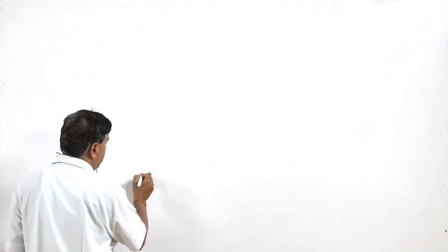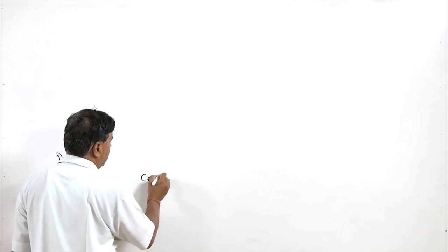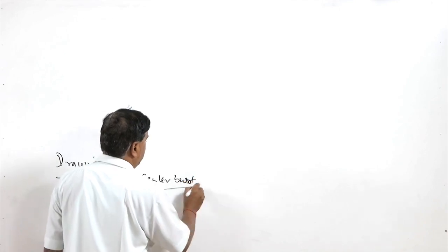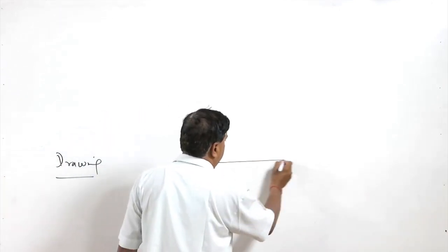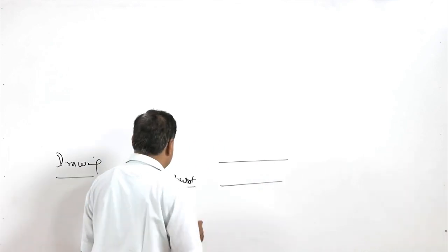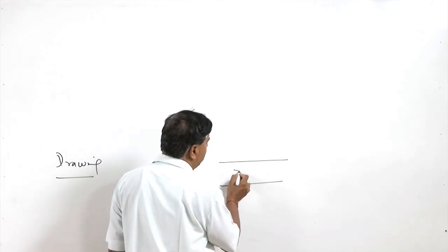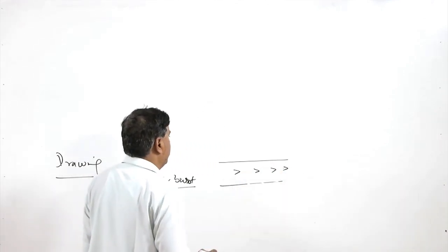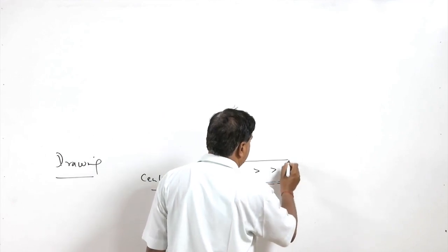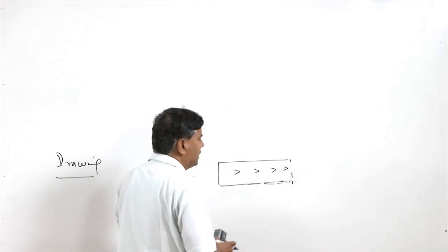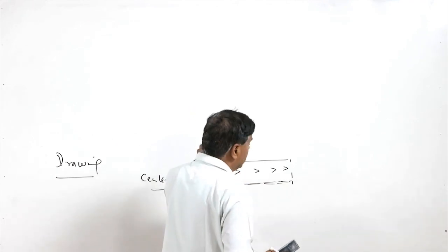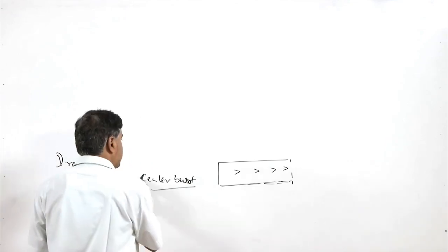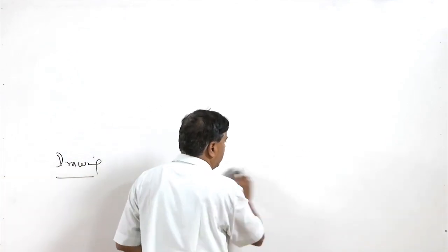For example, center burst is one of the defects observed in drawn wire, and it leads to the development of cracks, or chevron marks in the drawn wires, which, especially under upsetting conditions, will open up in the form of cracks.